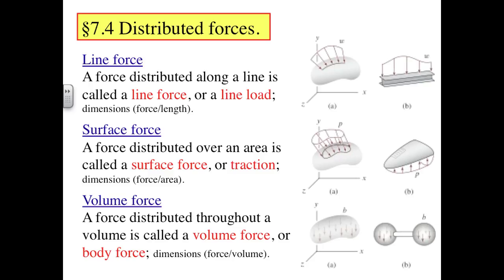Pressure is normal to the surface, but there is also a frictional surface load from shear stress tangent to the surface. The shear stress develops because the air flowing over the wing grabs the wing and must move with the plane's velocity at the wing's surface. The air then transitions back to zero velocity, moving away from the wing. We call this transition region a boundary layer, and the strength of the shear stress depends on the air's viscosity as well as the sharpness of the transition region.